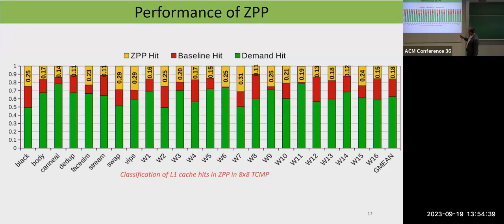And then, just to conclude with the results, 3 more slides. What we are showing is the number of hits that we observed. The green one is the normal hits that a cache has for the various workloads that we have taken. This W series is the workloads from SPEC, and these are from PARSEC. The yellow color is the extra hits, the percentage of hits that we got from the CPP expansion. Across workloads, you can see that CPP gets the benefit.